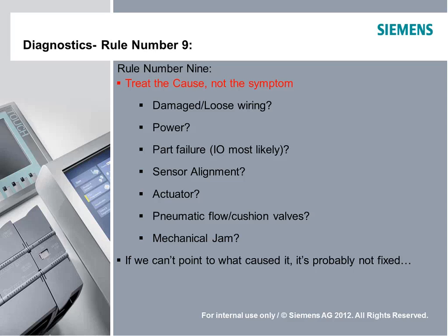That brings us to another point, two down from the sensor: pneumatic flows and cushion valves. That was really the problem there. The guy who had adjusted the sensor had done it at the extent of the cylinder, but cushion valves keep a pneumatic cylinder from slamming when it gets to the far end. When it gets very close to the end, there's an air valve in there that slows things way down. So if you set your sensor so it catches it just before it gets to that end, it's going to go right by it.